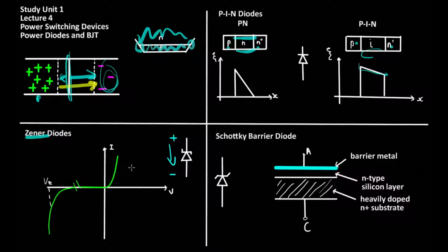Zener diodes are useful in low power electronics as clamping devices which will clamp a voltage across the terminals to some value which is designed into the device. In general, they are avoided in power electronics. Finally, the reverse Zener voltage is determined by design, and the symbol for the Zener diode is very similar to the normal diode with a slight modification to the crossbar around the triangle.